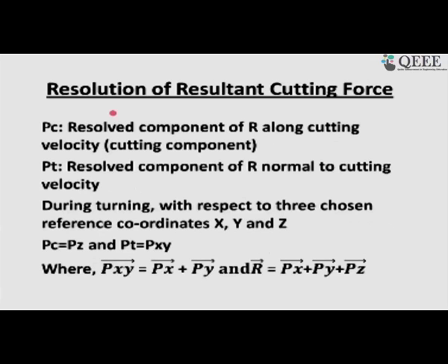Now, friends, this is something very interesting. We have noted the forces which are acting from two sides, from the tool side and from the workpiece side. However, ultimately what is of interest is Ps and maybe F, friction force, but we do not have any recording device or sensor along those directions. So, measurement of those important components, we cannot do.